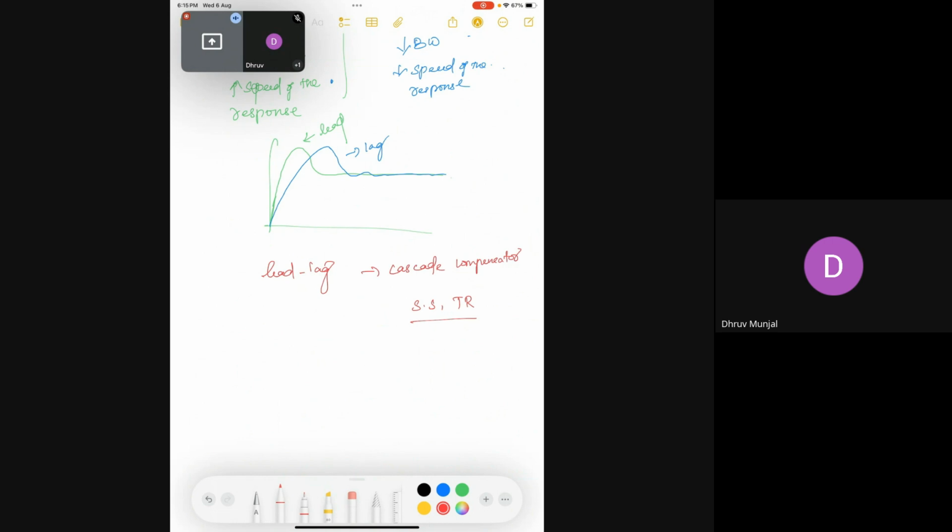But in some cases, this won't come. For example, the phase margin might be still around 20 degrees. So you would not get 40 degrees with only this lag compensation, whatever value you design. So at that time, you can change the values we assumed, like 0.01. You can change the value and see, but sometimes that will also not be helpful. So at that time, you have to design another lag compensator in addition to this, or another lead compensator in addition to this lag, or both ways. For example, if you work on phase margin first and you couldn't pull the gain margin, you have to design another lead compensation in addition to this lag. So that's how you will do all these lead-lag combinations.